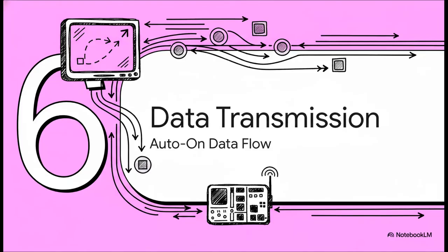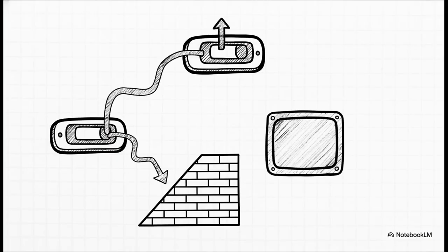Section 6. Map transmission and auto-on, data flow triggers. Here's a fundamental rule of the whole operation. The transmission of this vital navigation data, I'm talking about the actual missed approach legs and flight plan records sent to your navigation display, is entirely dependent on having the MAP display physically toggled to the on position. If it's toggled off, this data transmission simply doesn't occur.